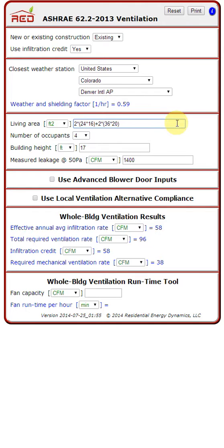Where I live in the Northeast, there are many basements that have a heating system, water heater, perhaps a washer and dryer. They are within the pressure boundary of the house, but they are not lived in. My advice here is, if the basement seems to be well connected to the living area upstairs, include it in the square footage of the living area. The ASHRAE standard is not explicit about the handling of basements that are not lived in.